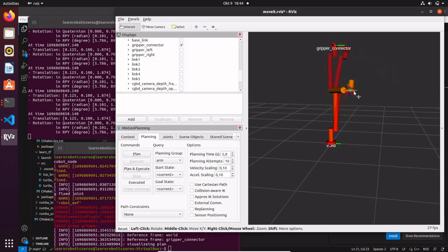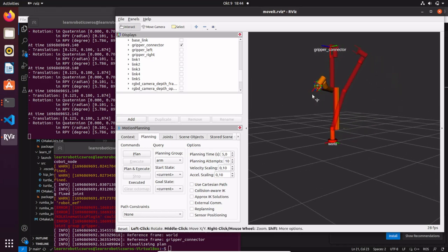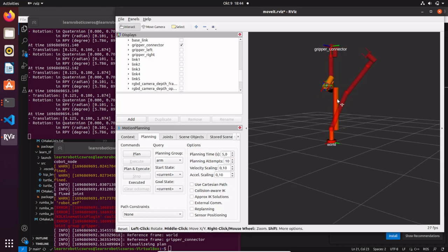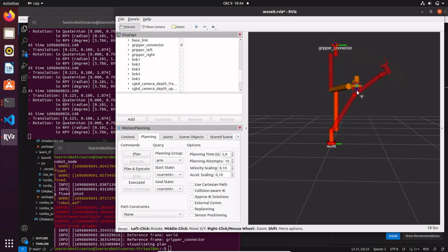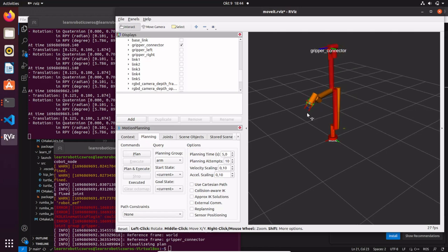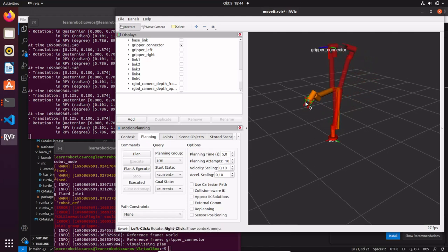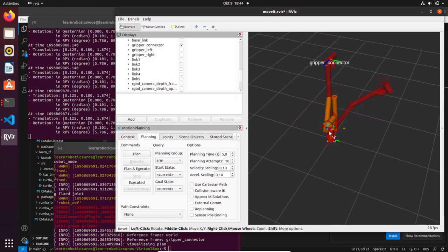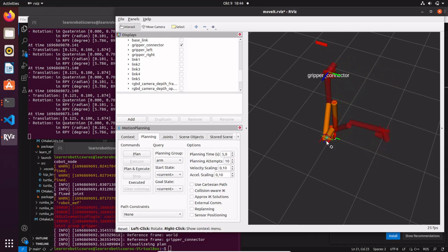So instead of using mathematical tools, we just need to set our TCP in the target position that we want, for example a pick position, and then check by echoing, let's say, the broadcaster that we have created, what is the position and orientation of the TCP.